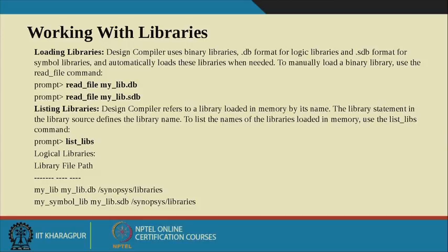Okay. So the next thing is working with the libraries, that means how you can load your libraries into the design compiler environment. Your design library will be saved in .db format, or the symbol library which has been created for your design will be saved in .sdb format. Synopsys design compiler automatically loads all these things. If you want to do it manually, you can write the command read_file mylib.db as well as read_file mylib.sdb. These two commands will read your library as well as the corresponding symbol library into the design compiler environment.